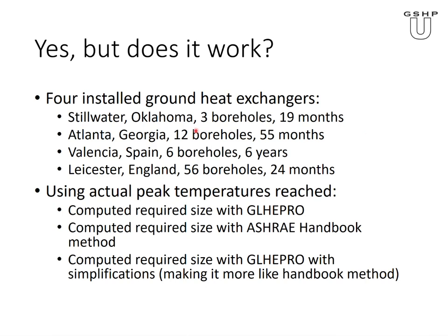The ASHRAE headquarters building had 12 boreholes, and it had run for 55 months. We had 55 months' worth of data. There's a system in Valencia, Spain, that at the time we had about 6 years. I think there may be 12 years now, but it is only 6 boreholes. And why do I say only 6 or only 3? In a system with only 3 or 6, there's not a lot of opportunity for long-term heat buildup or drawdown, right? So you don't necessarily see every effect that GLHEPRO can predict, right?